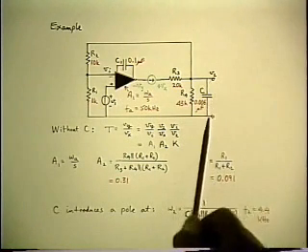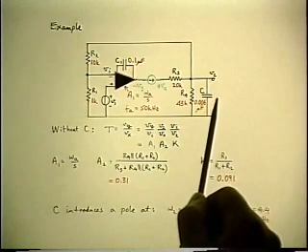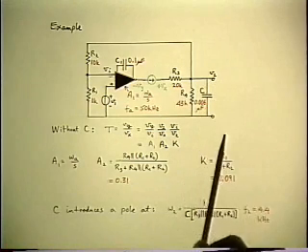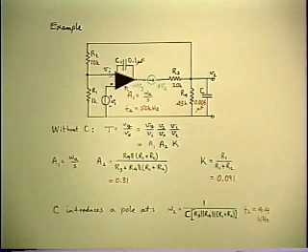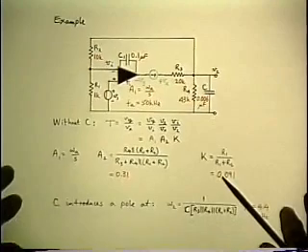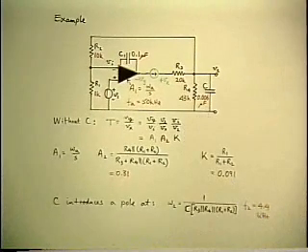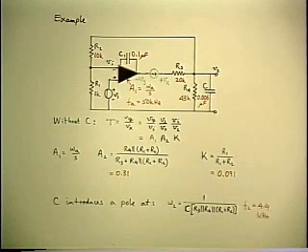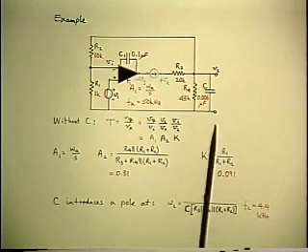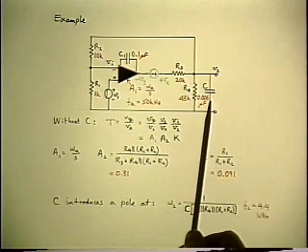Now, I left it out by replacing it with an infinite impedance, because it's in a parallel position. So again, mentally, we can go through all the steps of applying the theorem in order to restore it. Because it's going to give a pole and a zero, and each of them is going to be determined by the corresponding driving resistance.